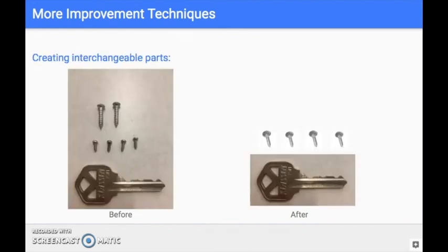In order to produce interchangeable parts for the flashlight, we propose that all screws be of the same size, in order to reduce the waste as well as the processing associated with picking the screws. As you can see on the left, the 2 screws on top are for the outside plate, and they obviously do not match the size of the smaller screws. This plays into the idea behind handling the screws, as one is easier than the other. However, on the right, all screws are the same size. Obviously, this would come with a little bit of a modification for the design, but it can be done.